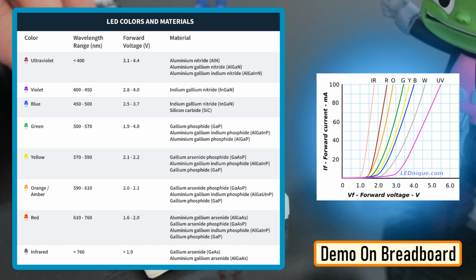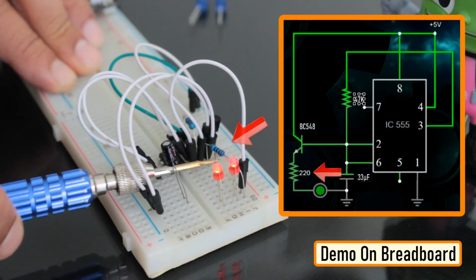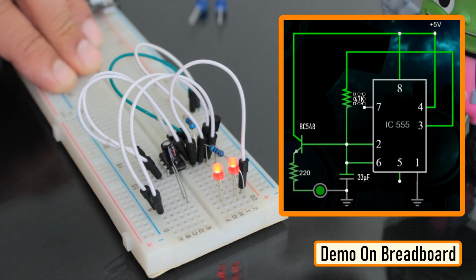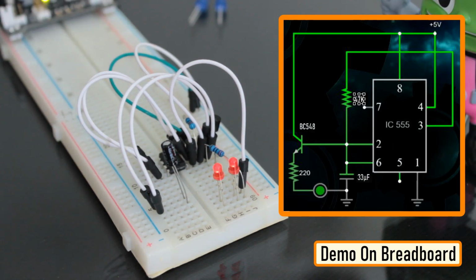If you connect a few LEDs in series, the forward voltage adds up and hence it will require more voltage to turn on the LEDs. You need to add a current limiting resistor between the emitter of the transistor and the LED to avoid an internal short circuit inside the LED.